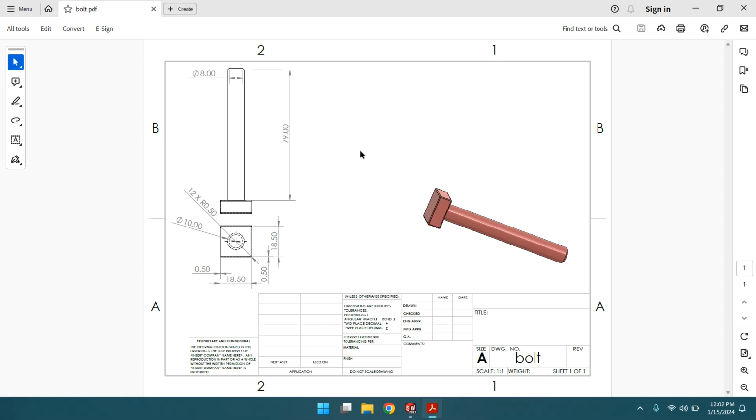Now let's create another part, that is the bolt. The bolt has these dimensions. The radius of the bolt is 10, and here is a chamfer of 1 mm, and the sides are 19, and after the fillet, it takes the dimension of 1 on both sides, so edges are 19 by 19.